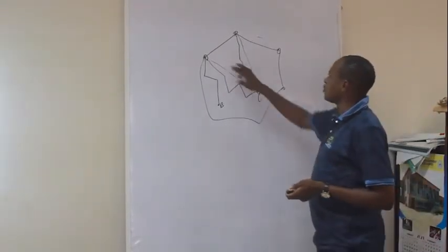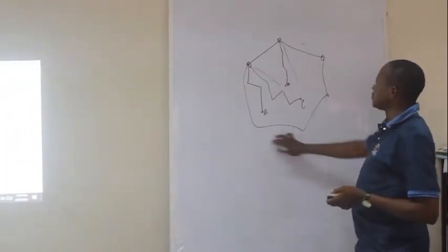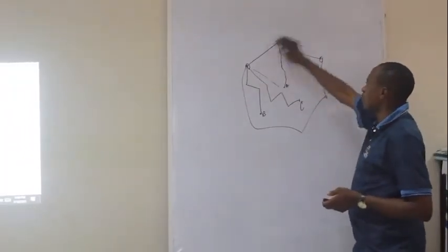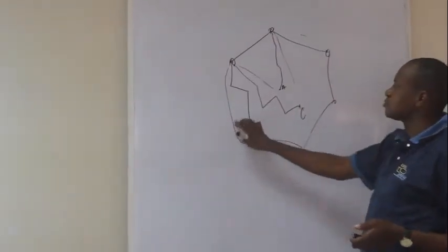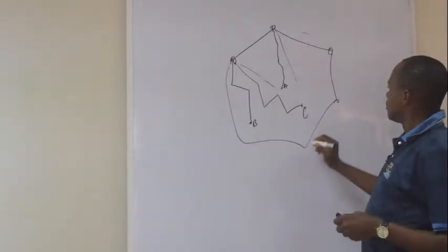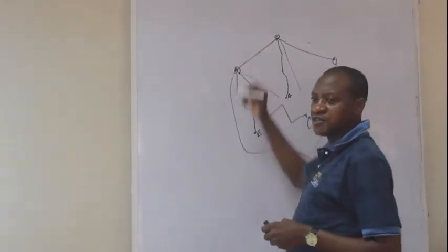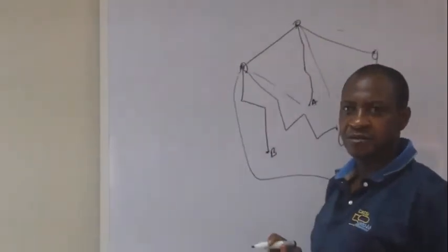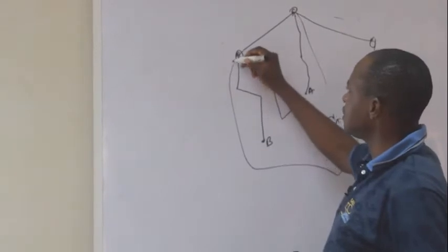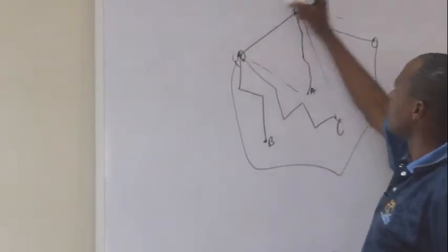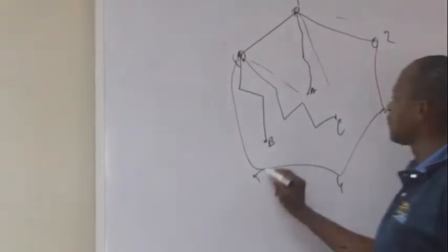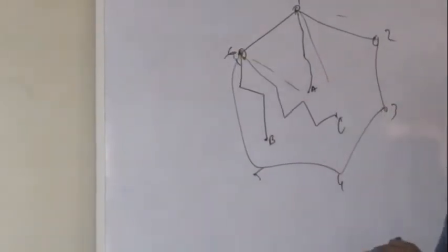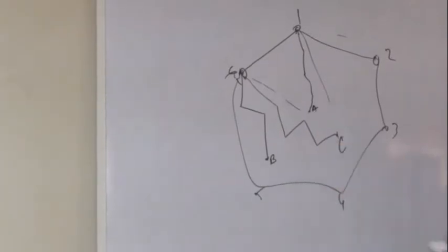In this case now, if you work holistically around the whole parcel, from the whole, if there's any error in the course of carrying out this work, you can adjust it if it is within the permissible limit. And once you adjust it, you can spread the error on all the points 1, 2, 3, 4, 5, 6. Distribute the error all over.